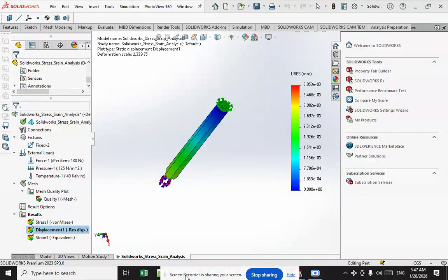In mechanical and aerospace engineering, however, stress analysis must often be performed on parts that are far from equilibrium, such as vibrating plates or rapidly spinning wheels and axles. In those cases, the equations of motion must include terms that account for the acceleration of the particles. In structural design applications, one usually tries to ensure the stresses are everywhere well below the yield strength of the material. In the case of dynamic loads, the material fatigue must also be taken into account.